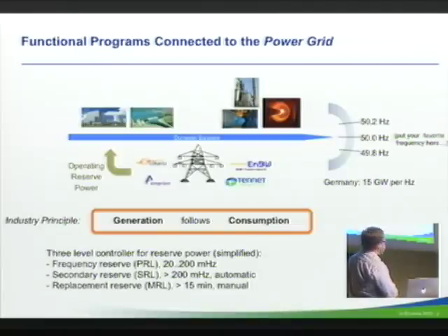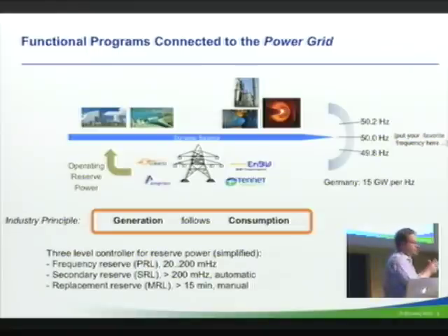If you think of a turbine driving a generator, the generator generates the 50 Hertz by revolving. Now if there is more load on the network, the generator has to work against more resistance, and that means that the net frequency goes down. To give you an impression, if it goes down by 1 Hertz, outside this primary reserve range, it would mean 50 gigawatt. And I will tell you what a gigawatt is in a second.